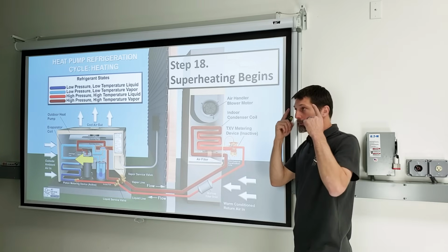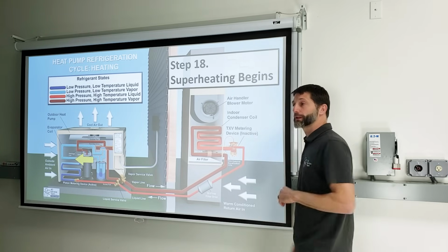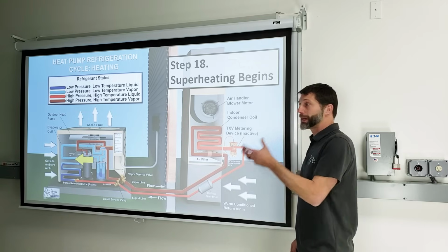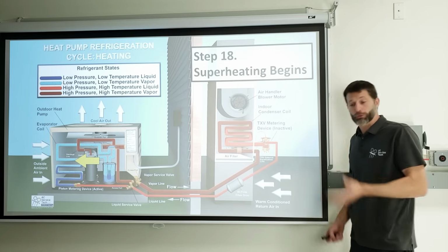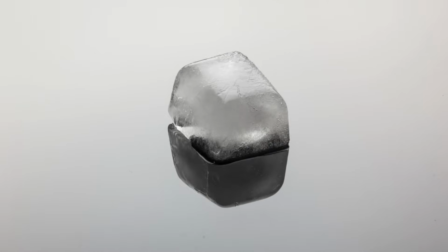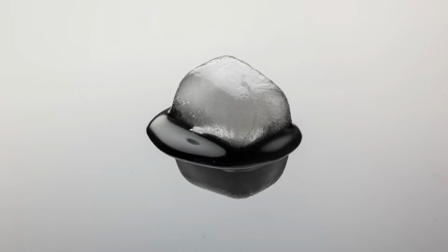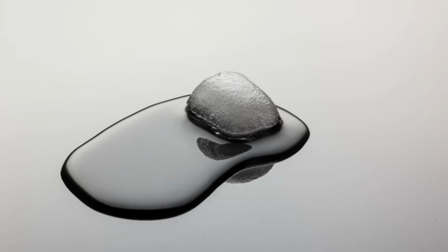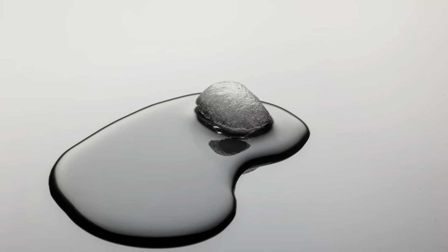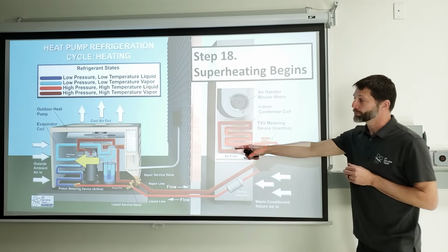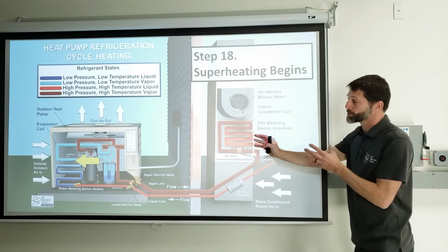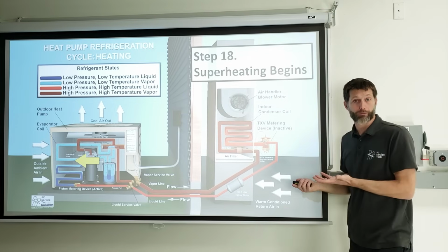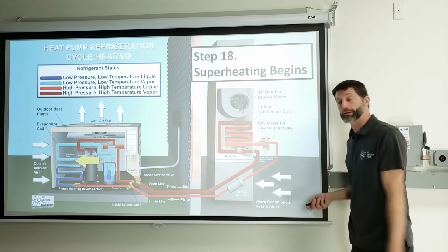And you could think about maybe an ice cube, like think about 32-degree water. How long is it going to stay 32 degrees if it's just water and you're drinking it? If you have it outside on a hot day, it's going to rise in temperature. But an ice cube is going to go through a phase change from solid into a liquid, and so it's going to be able to hold at 32 degrees a lot longer. So the amount of BTUs of heat energy that refrigerant is able to absorb from that low temperature air is significant, even though you have cold air outside, or it feels cold.